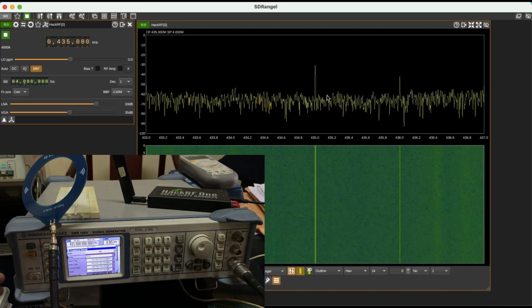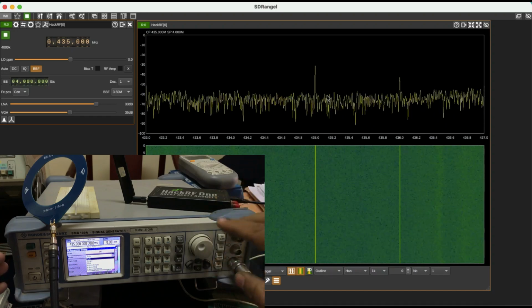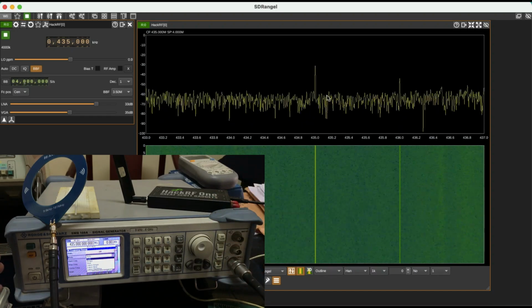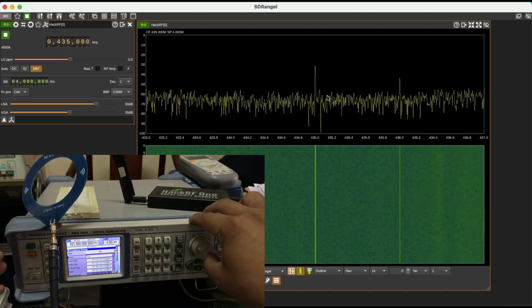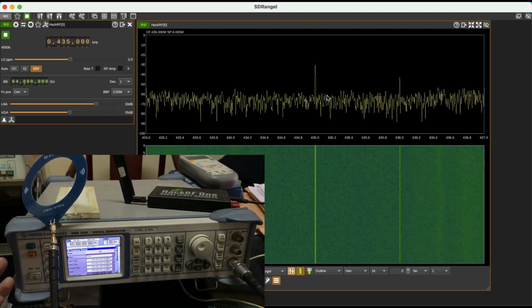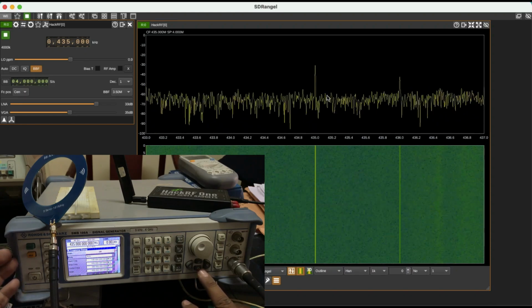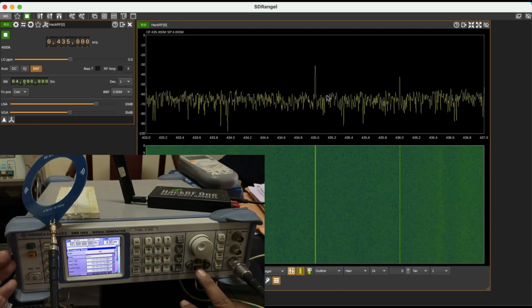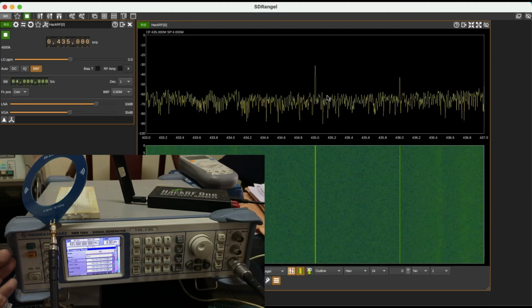I can choose a mode to be auto or a single step. I want to show you on that spectrum, so I'm going to leave it on auto, and leave the default frequency as is, because you can do a sweep from 9.9 kilohertz all the way up to 6 gigahertz using this. I can also do that as well, but let's do this.